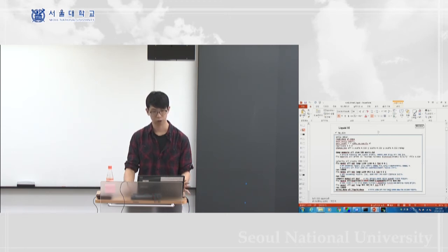So it's gonna give you the MSD of averaged values. And finally, we have to do the NPT simulation at the target temperature and target pressure for 10 picoseconds.